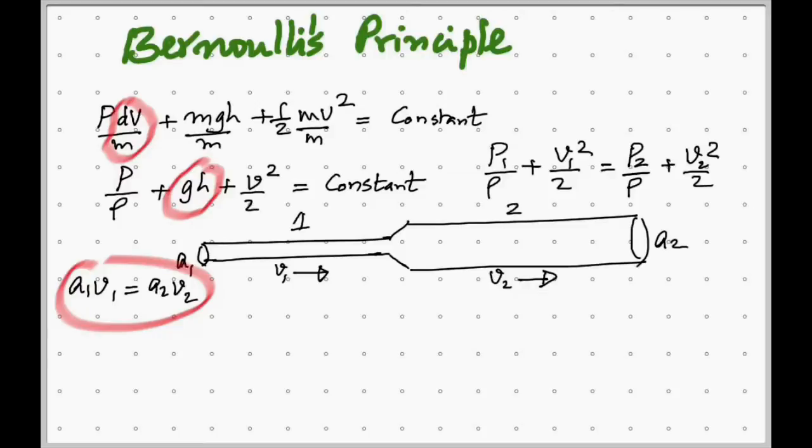Did you understand what I'm trying to say? So if P1 is given, or if you have to get P1, it should be the absolute pressure. And what you get will be the absolute pressure at 2. Okay, let me try to say it another way. If P1 is the gauge pressure at 1, P2 will not be the gauge pressure at 2. Let me try another one.